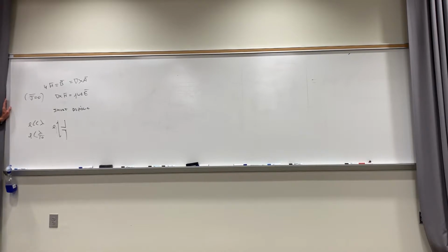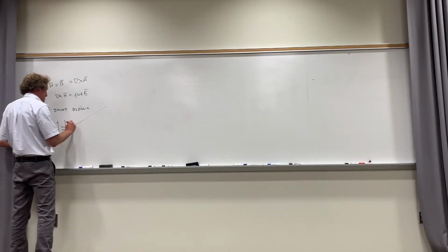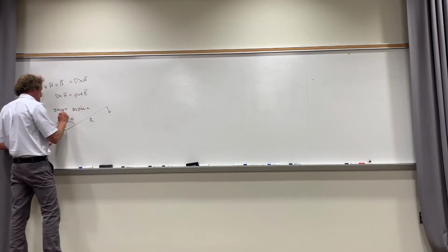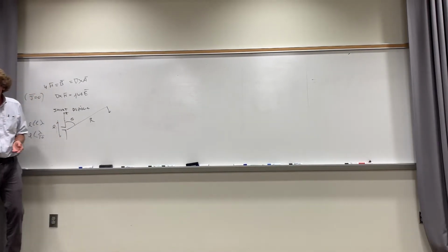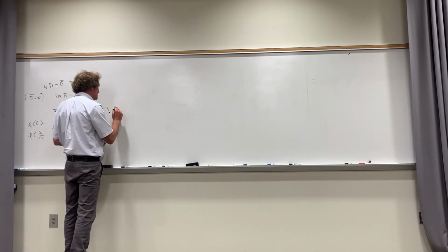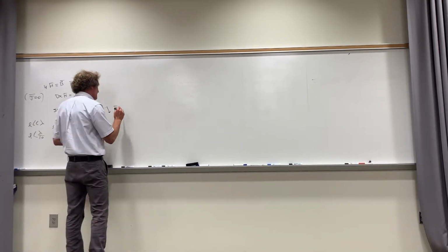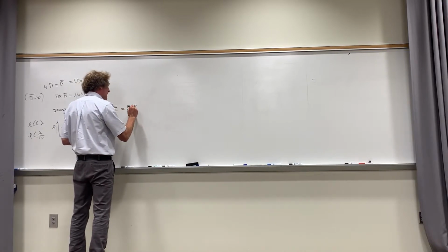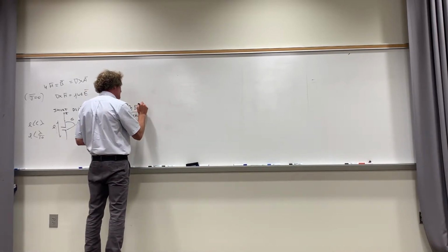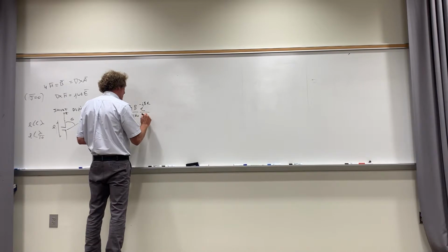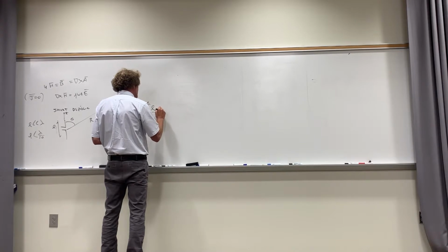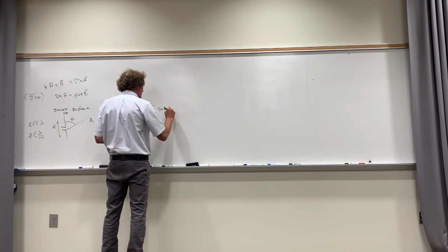Now, if we have a short dipole, then we know the electric field at a distance r from the short dipole, if the dipole is in the z direction, so I always assume the dipole's in the z direction unless there's a reason not to, is given by E equals j eta beta over 4 pi epsilon naught times e to the minus j beta r over r, times the electrical length L, times the sine of theta a_theta.